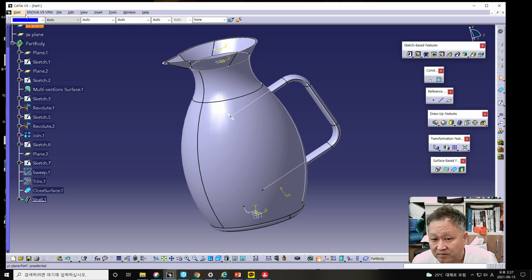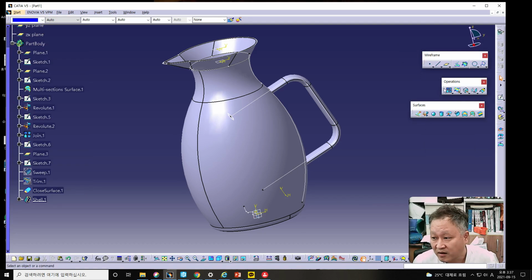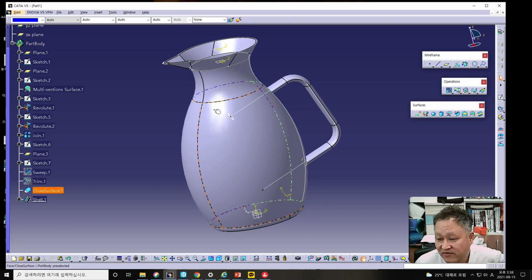the multi-section surface. In this case the coupling line can be made and 2 points should be generated in this case, and by using these 2 points and the coupling part, the upper entrance mouth can be made. Second, we draw the 2 arcs of it, and by using the Revolve menu we can make the body of the vase by using the Revolve operation.